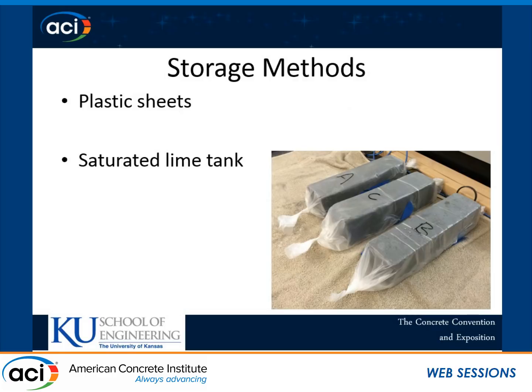Now I want to show some of our test results. The first question we had was, what do we do with specimens in the first day? The specimen was removed from the mold 5.5 hours after cast, and we want to keep the specimen as close to the standard test situation as possible. So we tried two methods. For some specimens, we wrapped them with a plastic sheet and made sure that the exchange of moisture was limited as well as we could. And for other specimens, we put them in a saturated lime tank.